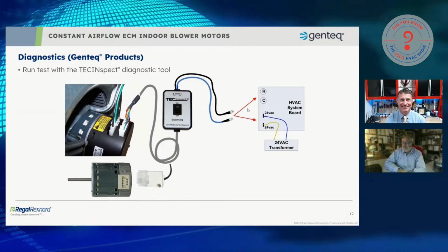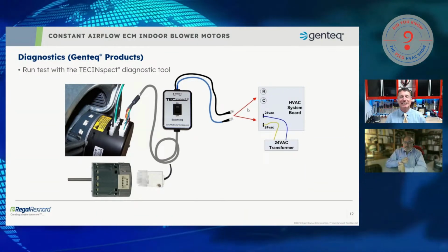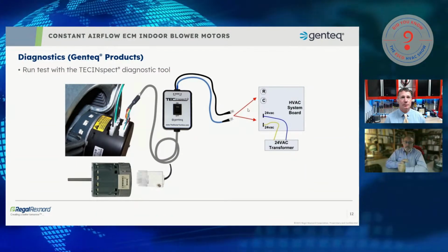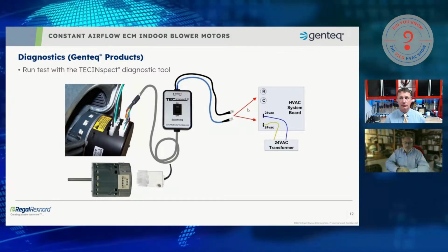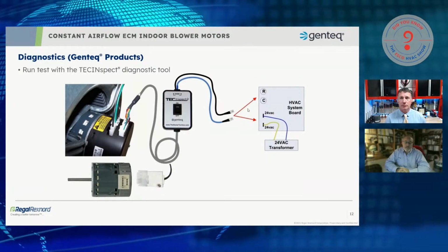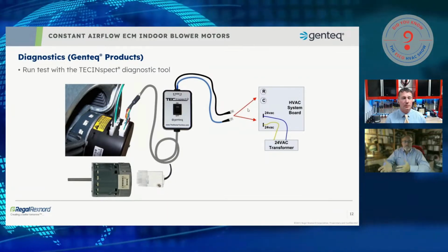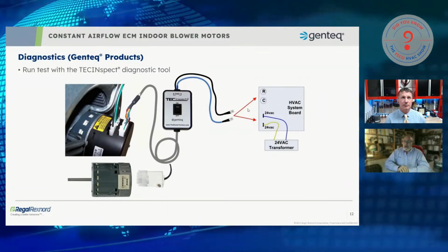You're out there. So as long as I have the alligator clips connected and a green light on the switch, then I'm going to flip the switch to the on position. And as I've already said, and you can logically figure out, if the motor runs, it's good. If it doesn't run, it's bad.